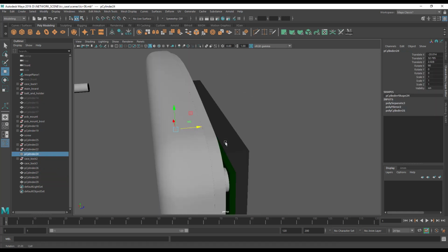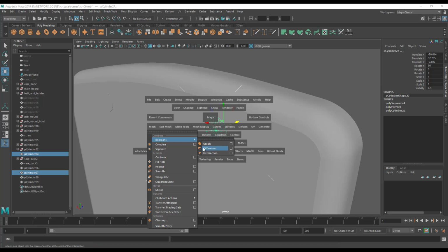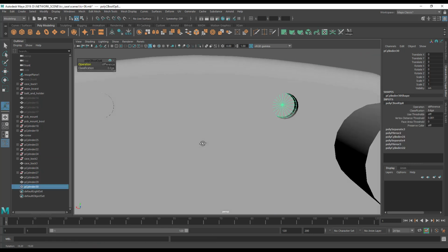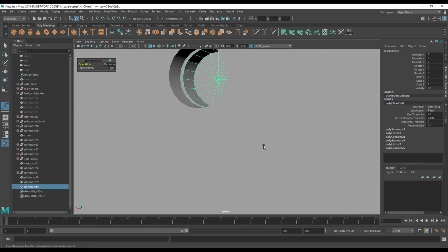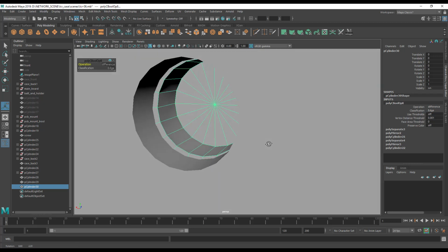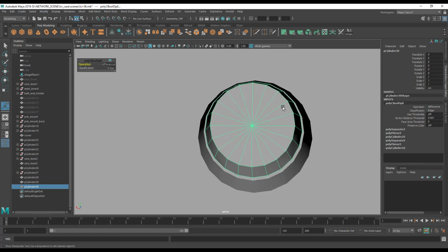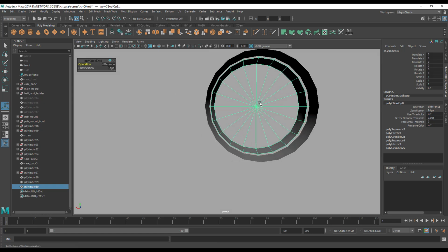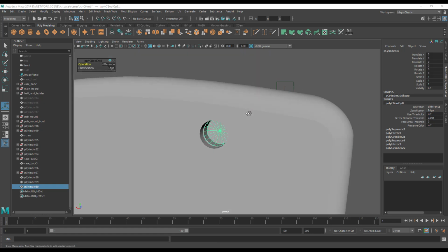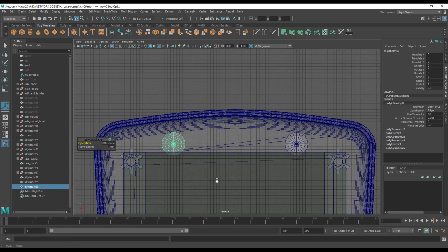So I'm going to make sure I select this one, and Mesh, Boolean, Difference. And you can see here, I now have room for my screw head to go 5mm into the case. Although why? What? Those should be exactly the same size. And are they? It's very difficult to see in this view. It didn't look like they were, but they may well be.